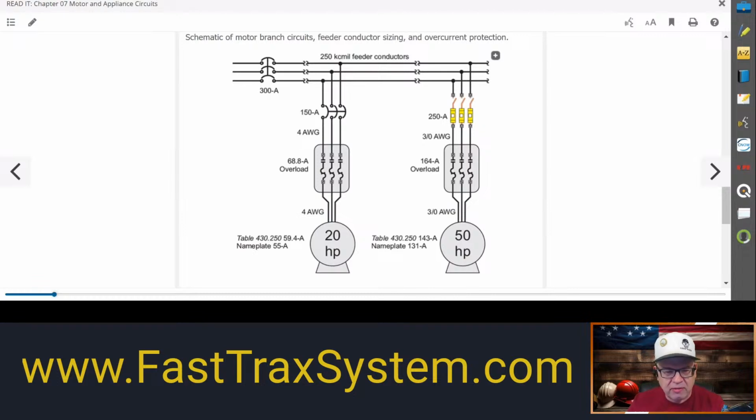Because the FLC is a fixed number. So it's kind of like a worst case scenario. If somebody comes and changes this motor, and maybe it's even a more efficient motor as time goes on, if we traditionally size everything based on the FLC, then we know that we're going to be okay, and that conductors are going to be sized more conservatively than they possibly would be for something like an FLA, which is on a nameplate and can change for the motor.